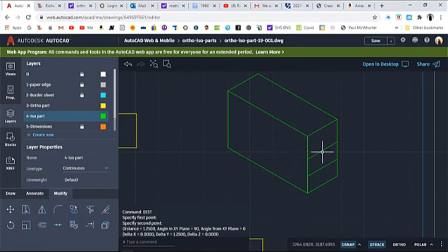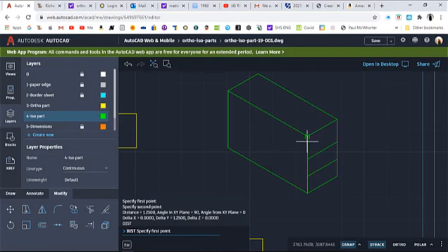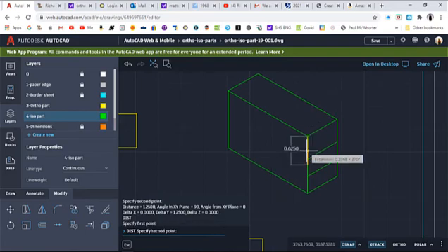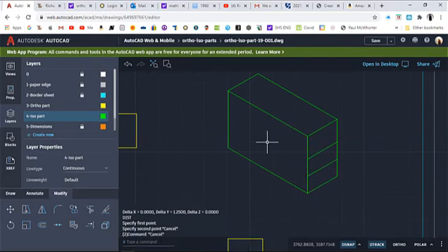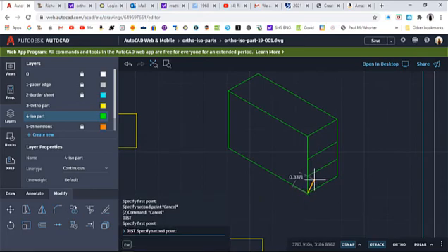So let's check this measurement here. I'll hit my spacebar again, and I'll bring up my distance command. Measure this down to, it's 1/2 inch. I did something wrong. Okay, let's hit escape. I thought something didn't look right. Hit the spacebar again, measure here to right there, 3.75. That's good. So we got this in the wrong place. We're going to take care of that.